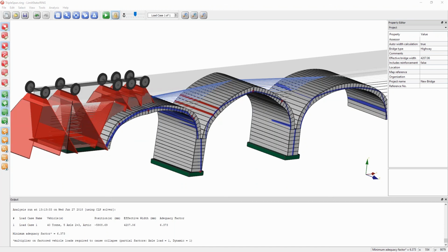material. The caveat is it's a bit like in reinforced concrete. If you over-reinforce a section, then you can end up with, in that particular case, a brittle or explosive failure of the concrete section. So you can change the mode of response quite significantly. If you put in a relatively small amount of reinforcement, so it's lightly reinforced, then you can expect the mode of response to be largely similar to the unreinforced case, but with a slight uplift in load carrying capacity.